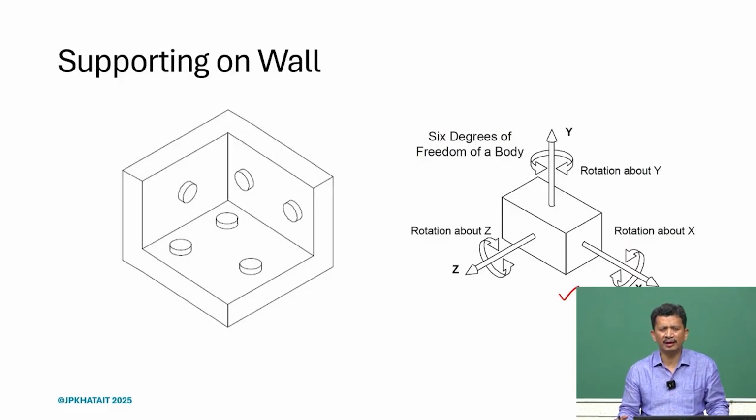And many times when we are talking about precision machine design, we resort to precision components, and we define very tight tolerances for each and everything. What we realize is that if we understand kinematic design, or kinematics, we may not have to do that. Just by defining the contact points, we should be able to constrain it properly. And then what we have to emphasize is to focus on designing those contact points or contact surfaces.